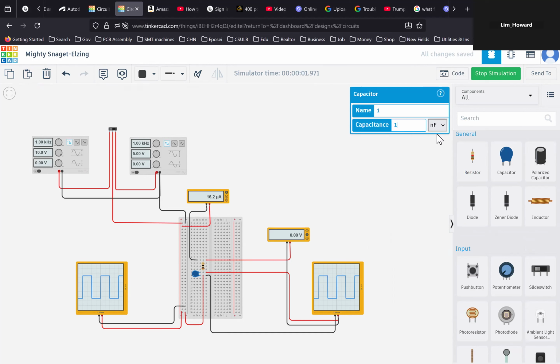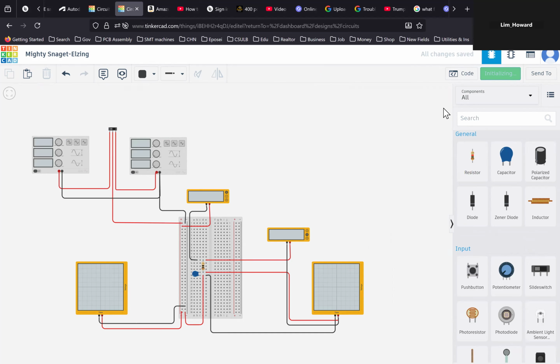Okay, so now based on this one, trigger, you see now this input and output. As you see, because of low capacitance and resistor, the time constant is low, so that's why we don't see much slope at the beginning here and then after that.